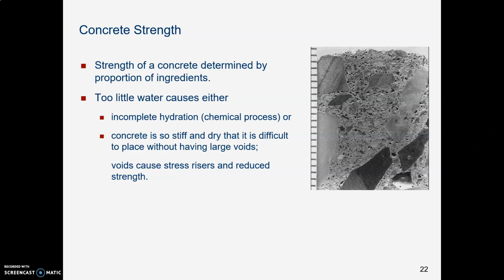Crack propagation is an issue in concrete, and what we're worried about is if we don't get the water mix right and we get little holes in the concrete mix, they can be sharp cornered little things and cause stress risers, and then you have weak concrete.